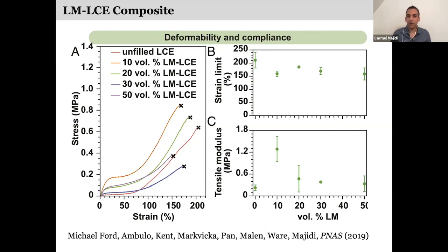However, this is way smaller than the types of stresses you can support with shape memory alloys like nickel titanium. In the austenite phase, those materials have a very high Young's modulus, on the order of tens or even hundreds of gigapascals. Now, granted, the strains aren't quite as much, so you'll be multiplying that Young's modulus by a much smaller number to get the effective stress. However, even then, we're still talking on the order of hundreds of megapascals, even gigapascals. So at least 2, possibly even 3 orders of magnitude more force.